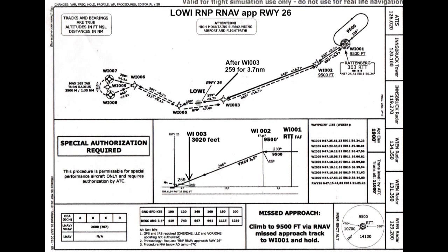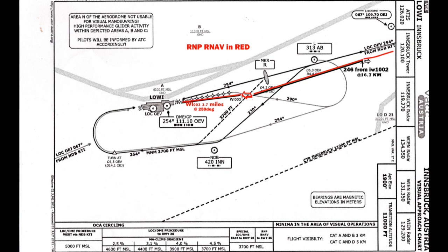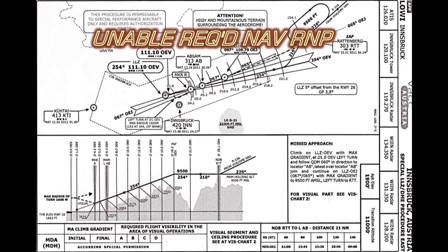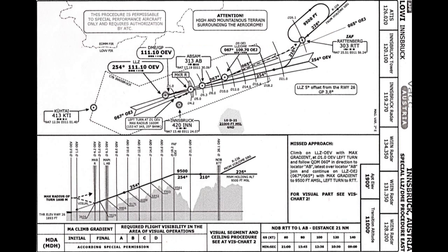Ground proximity warning system alerting is provided on IAN aircraft. During the IAN approach, the GPWS glide slope alerting provides alerting when the airplane deviates below the glide path before reaching full-scale deflection. If you see the warning flag on the FMC, Unable Required Nav Performance RNP, once this alert is seen and suitable visual reference has not been established, a missed approach must be executed. The final approach is very similar to the ILS final approach.